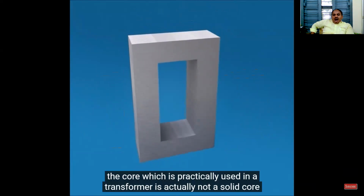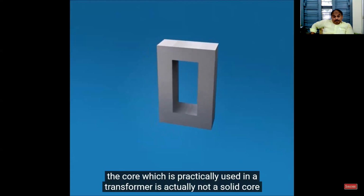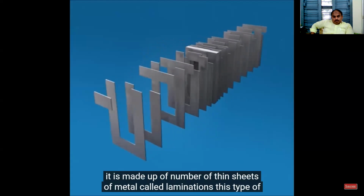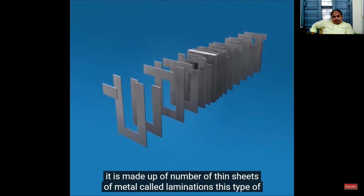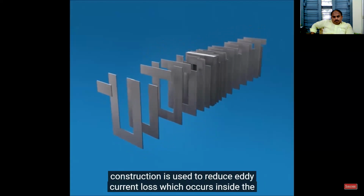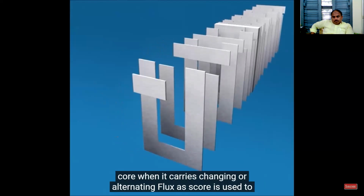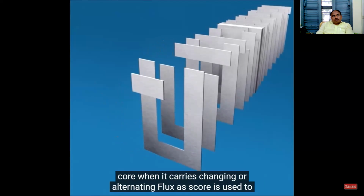The core which is practically used in a transformer is actually not a solid core. It is made up of a number of thin sheets of metal called laminations. This type of construction is used to reduce eddy current loss, which occurs inside the core when it carries changing or alternating fluxes.